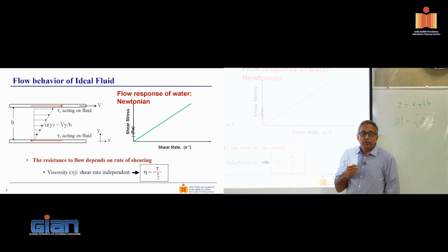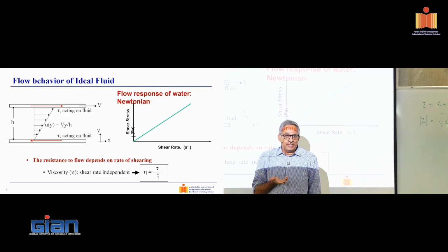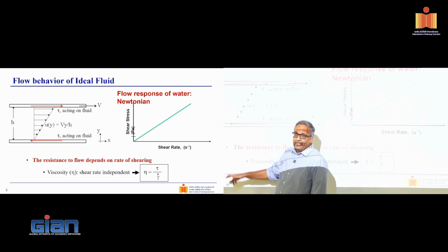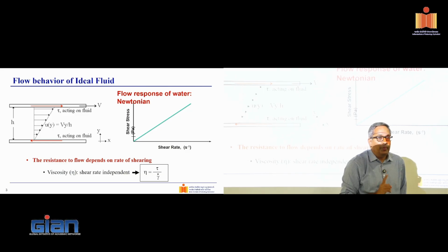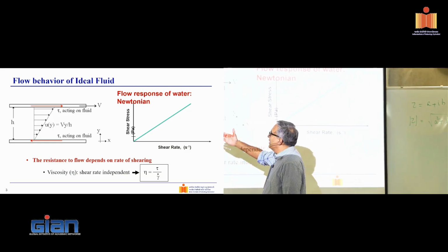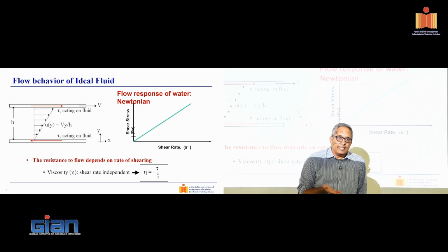Okay, so how do we measure shear rate? Well, I have to infer it. I cannot directly measure it. How do I infer it? Well, assuming that I get a linear velocity profile, I can calculate what is the shear rate that's happening here, right? That's how I calculate the shear rate.